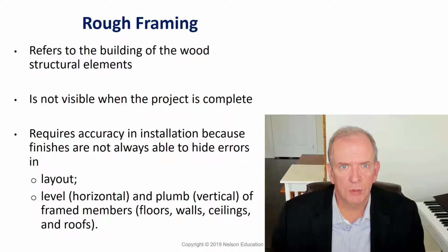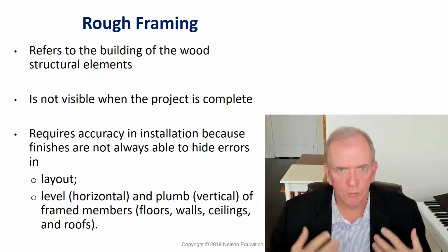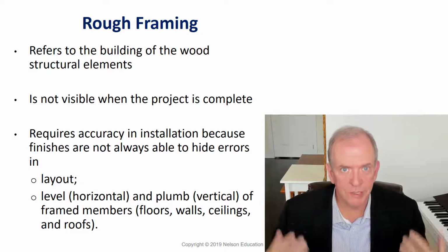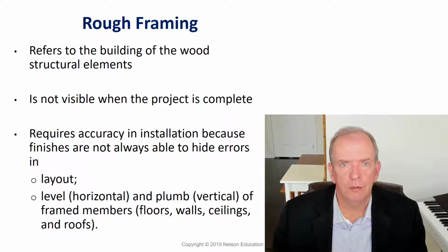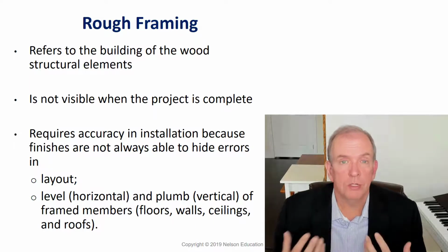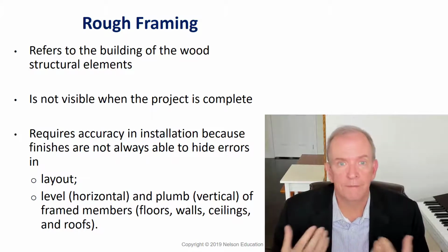But then nobody really wanted to certify the buildings after the earthquake because it's hard to look at reinforced concrete and determine the extent of damage that may have occurred from the first earthquake. So they could design it to survive a dramatic earthquake, but could it survive a second one, and who wants to take responsibility? So they rebuilt most of Christchurch using wood frame construction or engineered lumber like cross-laminated timbers, etc., as we'll talk about later in the course. So there is a lot of advantage to wood construction because if there is an earthquake, it's easier to identify where the problem is and fix it.